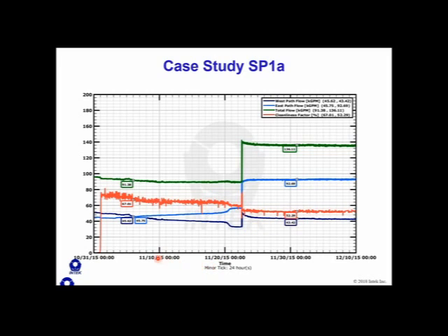So what happens typically when you get debris fouling, something that gets into the cooling water and blocks up tubes, is that debris typically follows only one path of the cooling water. The debris wants to stay straight in the cooling water pipe, so it tends to go to the very last water box in the cooling water chain. The west box is actually the furthest from the cooling towers at this plant. So that debris continues on straight, takes that elbow up and turns into the water box and goes into the condenser, and it preferentially fouls the west path.